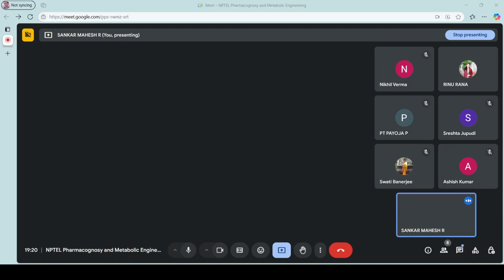So this is how your flame ionization detector looks. Earlier we saw what the gas chromatography chamber looks like. You inject it, a gas carries your injected sample, it goes through the column, and depending on the affinity, some of it will elute first, some of it will elute later. Now, in this detector part, we have the flame ionization detector.